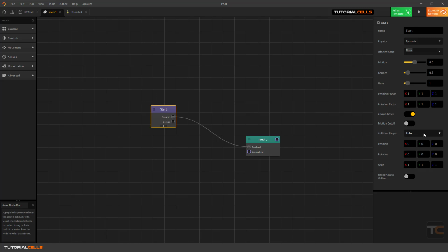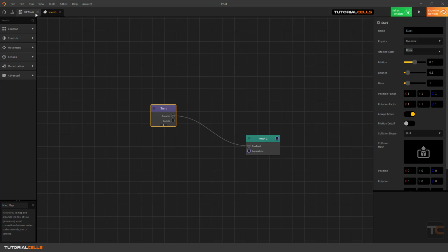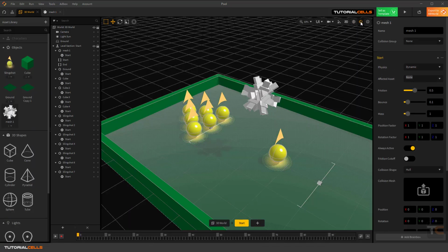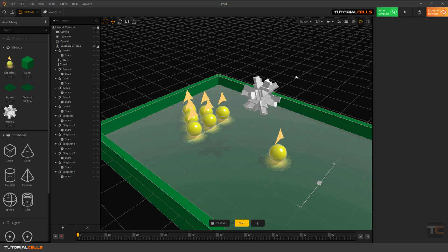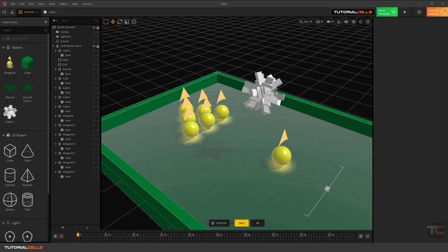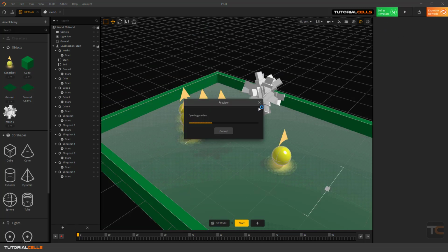But go to this object, it's in the start, nice. And the collision shape of that, you can see this object is not a cube, it's not a sphere, it's not cylindrical, capsule, or hull. You can make it a hull. Okay, make it a hull object. It means we can close that. Collision shape, it does not have any collision shape. It actually creates a bounding box of that object, not holes and something like that.